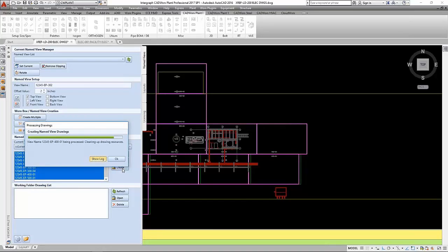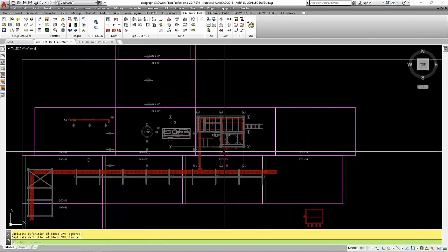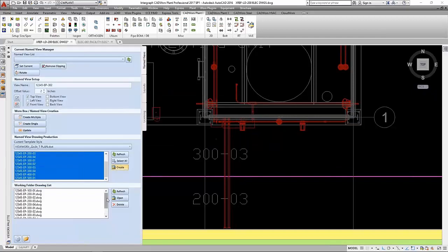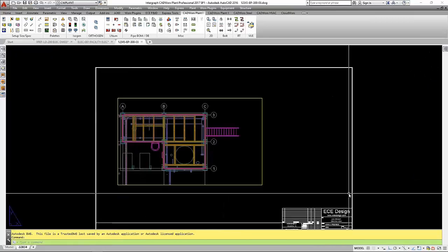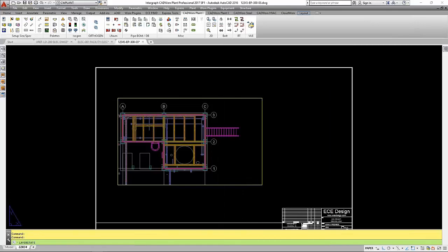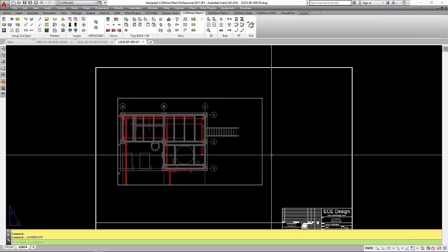So just click the Go button and create, and I've just created a top view or plan view for every area. I'm going to zoom into area 303 again, so I'm just going to go find that plan, and now I'm going to open that plan, and this gives me a top view for that. I've got some work to do in this drawing, but the first thing I'm going to do is just change a layer state, because in my XREF I was committed to a layer state, and this will change everything to red and gray, which I'm going to use for all of my production drawings.